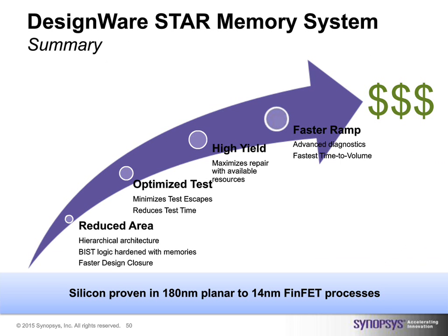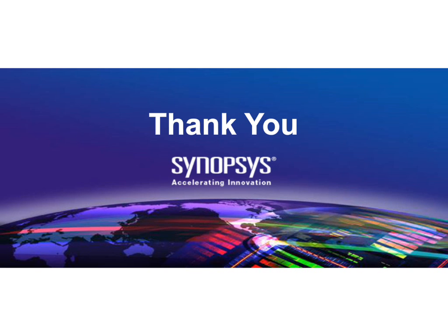Looks like our first question for you is, Yervant, would the STAR IP results also be integrated with Yield Explorer? The answer is yes. Yield Explorer, for the larger audience, is a Synopsys product that handles yield data, does the analysis, the classification, the visualization, and so on. And as we analyze the outcome of the testers, the SMS, or the Star Memory System Yield Accelerator, does the debug and diagnosis on the outcome, interprets the results, finds out the exact location of the defects, as well as classifies the faults and so on. All that data would pass to Yield Explorer, and Yield Explorer will be able to handle the classification of those, the statistics and the visualization at large scale for many chips, for large volume wafers and lots.